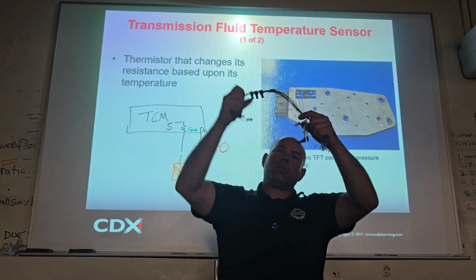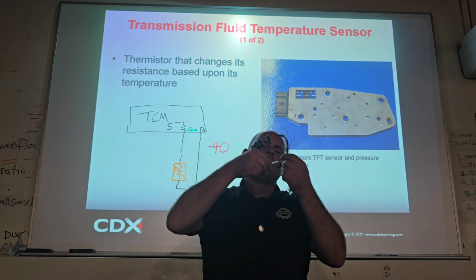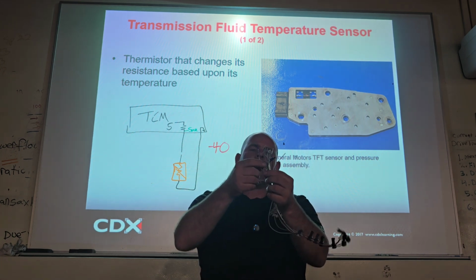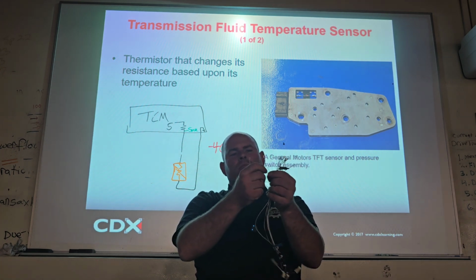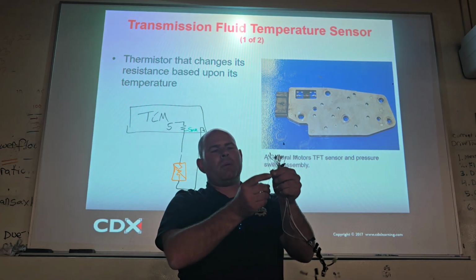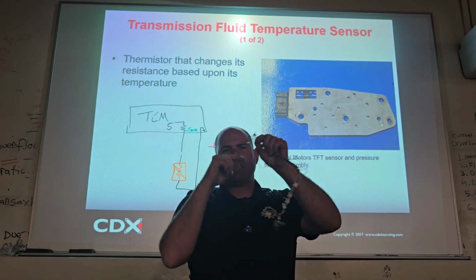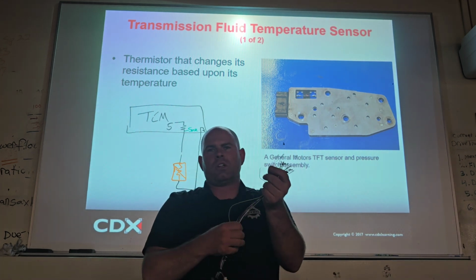And it also could be one of these wires, right? These wires were orange. So it could be one of these wires. It could even be a pin fit issue, right? If these are the female pins and they're kind of opened up and the male pin is no longer really making good contact, that can give you the open circuit as well.